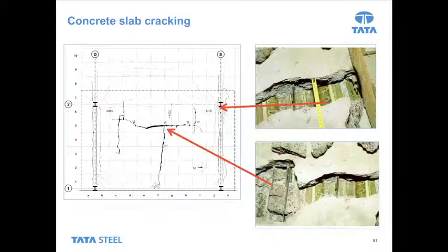This is a photograph, or a couple of photographs, of the compartment floor from above. So some rather large cracks there in the slab, a little bit bigger than you might be comfortable with normally. But again, the good news here is that the integrity of the compartment, the integrity of that floor wasn't infringed. So there wasn't fire spread from the compartment where the fire was taking place to the compartment above. And that was provided for by the metal deck and the mesh reinforcement to some extent.